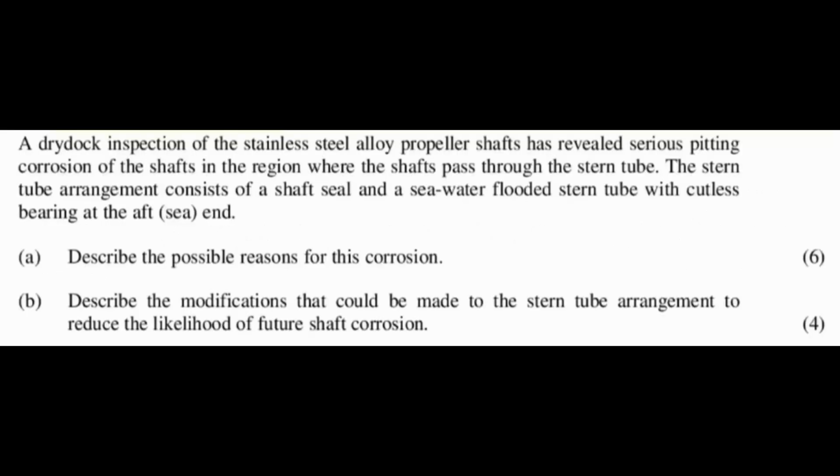A dry dock inspection of the stainless steel alloy propeller shafts has revealed serious pitting corrosion of the shafts in the region where the shafts pass through the stern tube. The stern tube arrangement consists of a shaft seal and a seawater flooded stern tube with a cutlass bearing at the aft sea end.